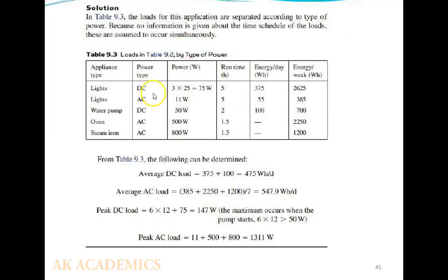If the power rating for the water pump is 50 watts, is that the maximum power consumed by the water pump throughout the day? No. This may be the average power, but what is the peak power? We have to find that power at the 6 ampere start current and compare it with this 50 watt.